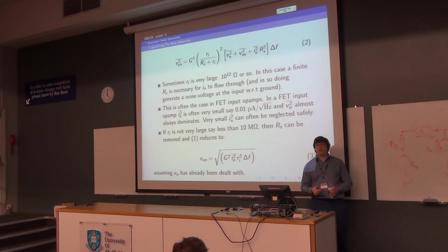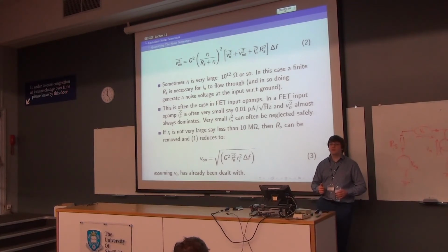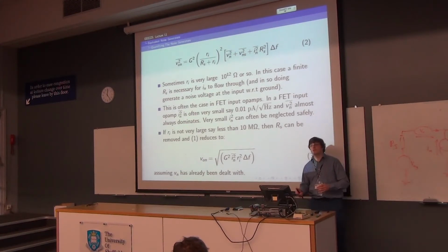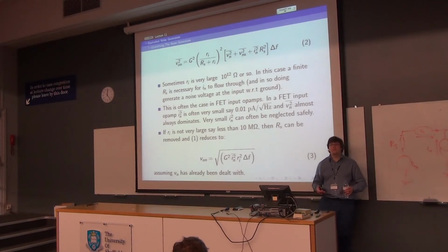And that means if you think it's low, but I don't know how low, I can accept an Rs of 10 ohms will not make too much difference to the noise, you'll pop 10 ohms in there just to make sure you know it's about 10 ohms. If you knew it was sort of less than an ohm before, 10 ohms plus less than an ohm, about 10 ohms.